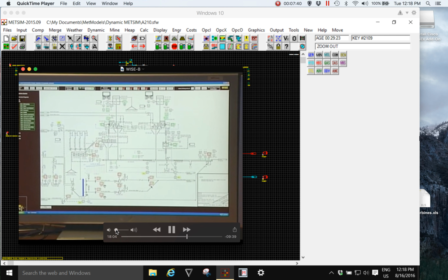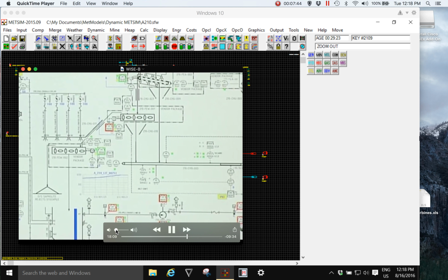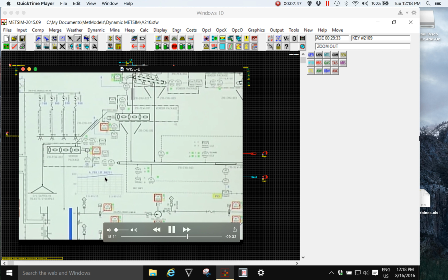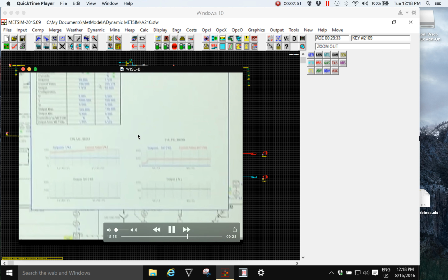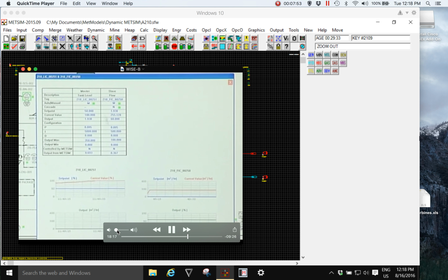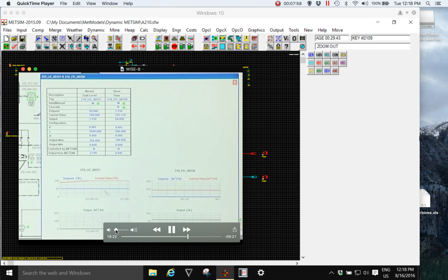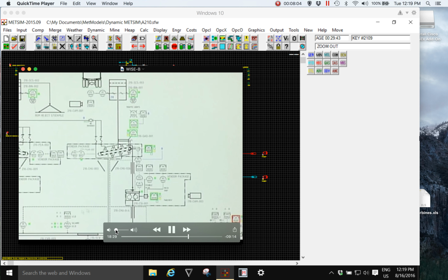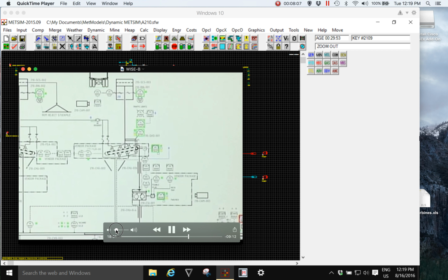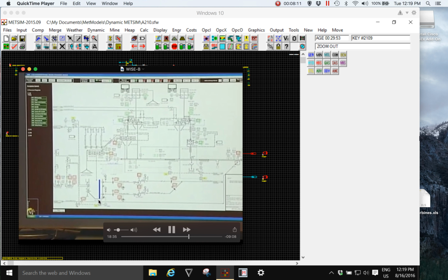It's calculating the flow rate for those conditions, upstream and downstream, and it's providing that dynamic value, as you can see level changing here and other things changing, and it's providing those dynamic values back to the SCADA system onto the live PNIDs, and is also providing that data into the 3D walkthrough model. Able to drive the plant and see what the consequences of all your actions are.